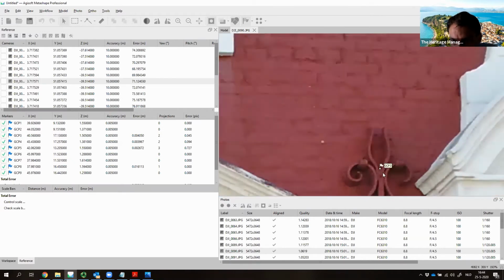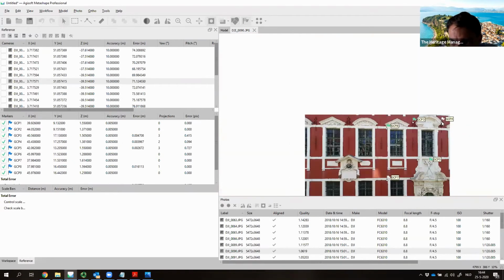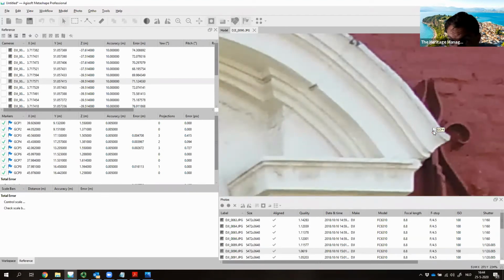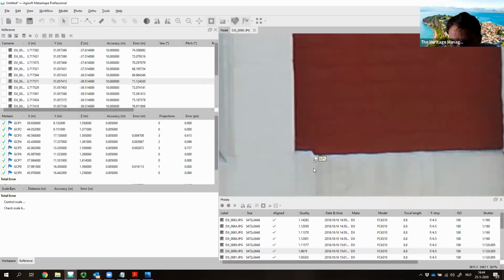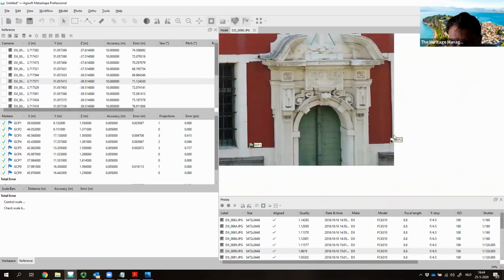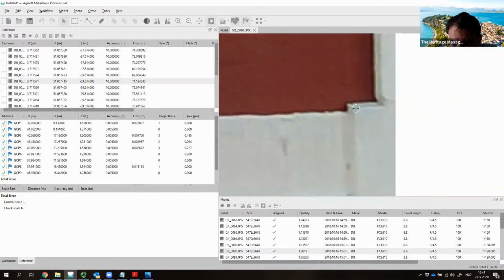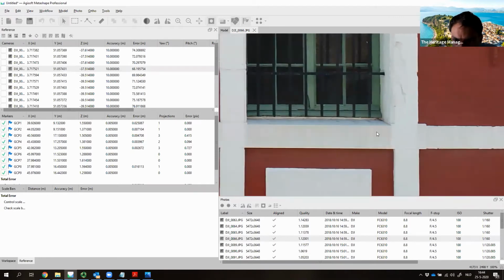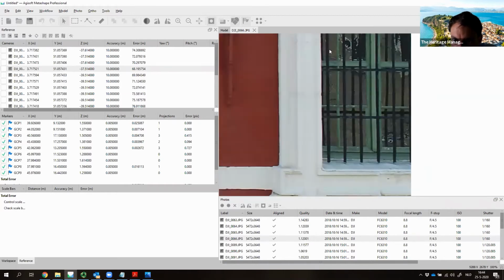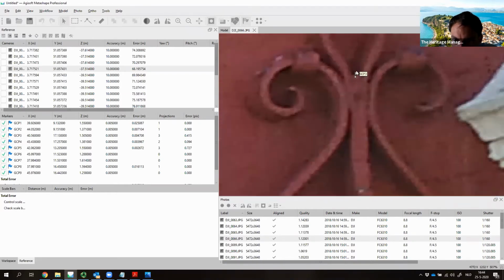Point number 3 was also a very obvious point. Point number 4 is clearly not visible, so don't touch this point. Also don't remove it. All the estimated points are not incorporated in the process. This can be used, point 1, used here, and point 2 can also be used. It's actually also the crossing of this point. And by doing that, you can just go to different photos and assign the different coordinates to certain pixels.